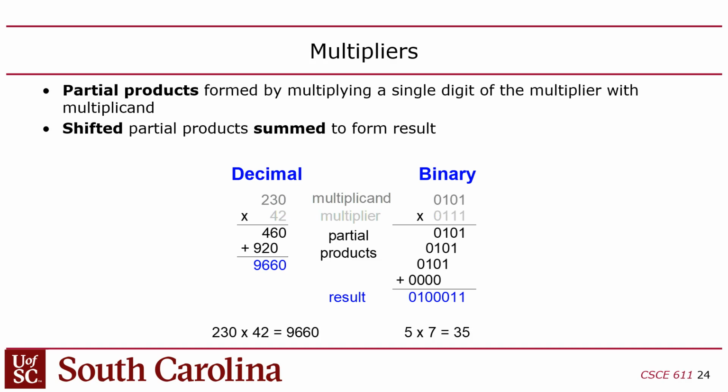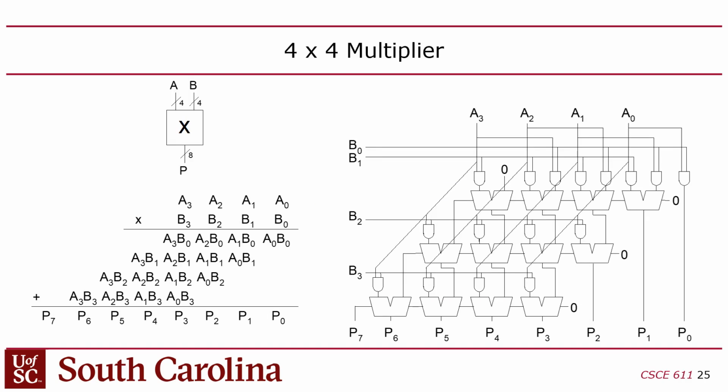So basically, all a multiplier is in binary is just a shift adder, right? All you do is you look at each bit of the multiplier, and for each bit that's set to 1, you just add a copy of the multiplicand shifted that amount. So that multiplier is fairly simple. The problem is that it's expensive because you have to have 1 adder for every bit in the multiplier, right? So that's an issue. It makes multipliers expensive.